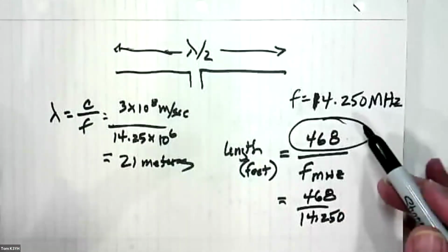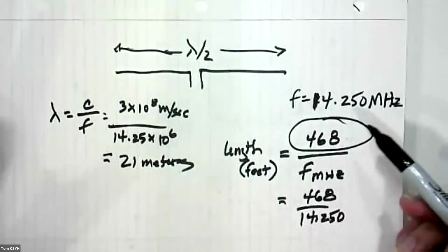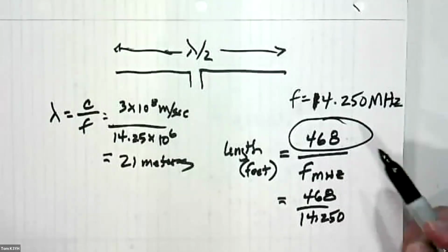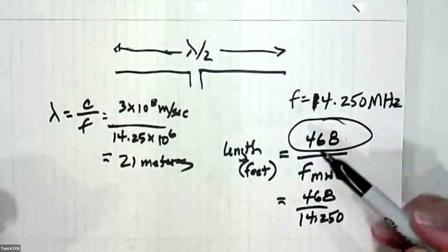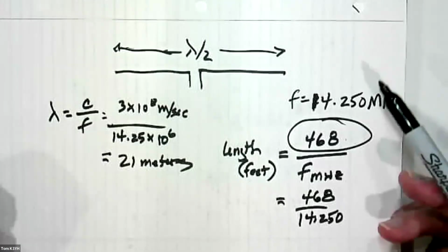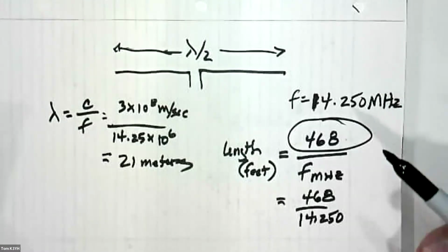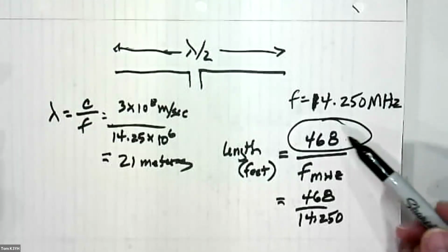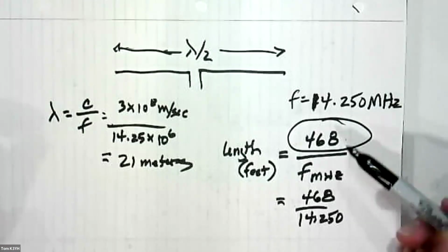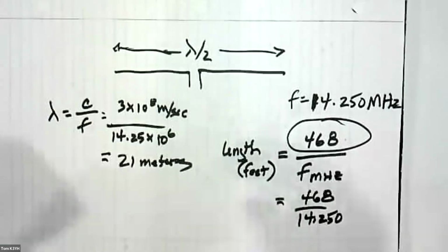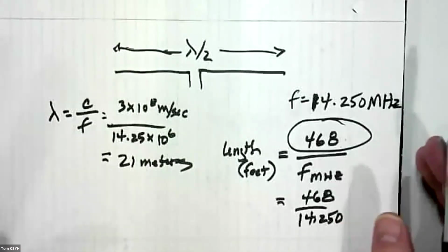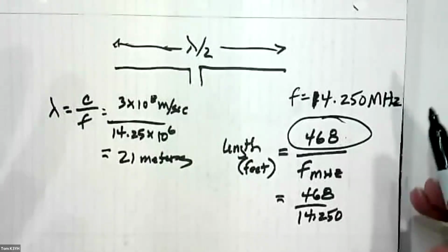When you're actually building an antenna, the other number, 492, will give you a more accurate answer. But when you're building an antenna, you say it's 33 feet, just make it a foot or 2 feet longer, and then you can shorten it up to get the lowest SWR. You should always make it longer because you don't have to cut it to shorten it. You just bend the wire back on itself and wrap it, and it'll work just fine. Since it's getting late, I'm not going to extend the discussion about it.